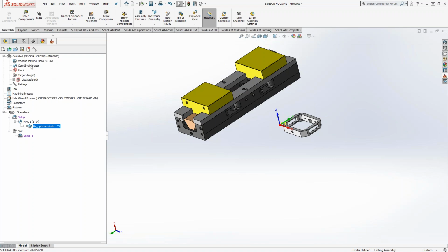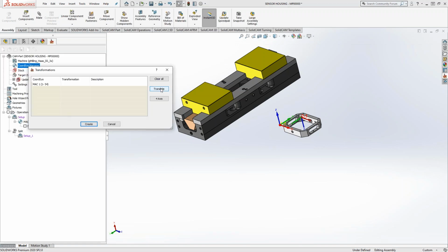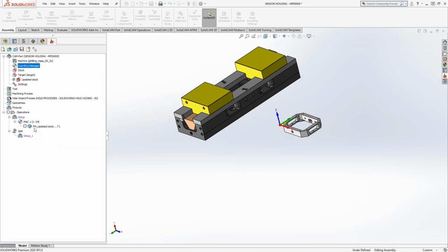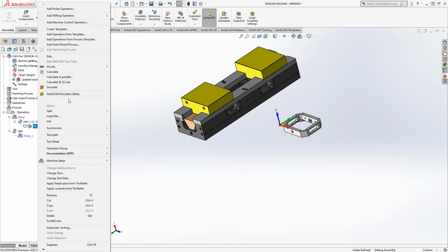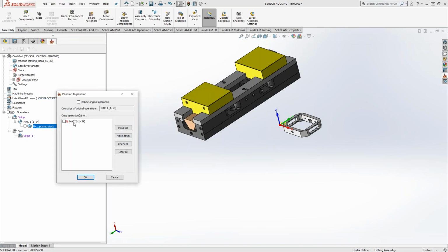There is a way to set up multiple coordinate systems. You can use transform here as well. You have the ability to do a translate of all your coordinate systems. You can get all those coordinate systems in one click, and then when you do your coordinate system transform, you're just basically checking them off in the list. You'd have them all listed here, and you just do check all, and then you can transform it across all the coordinate systems.